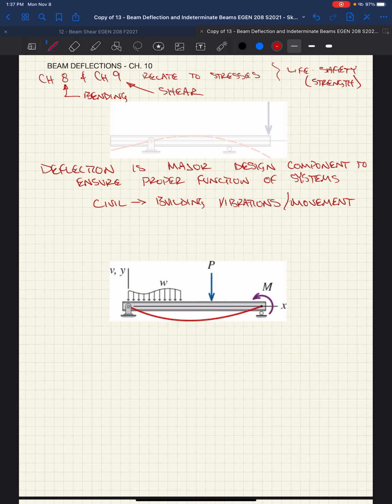So I've mentioned in the past, like ponding of roof systems. If it rains, the roof deflects. If the roof deflects, it no longer sheds water, say to the outside edges, scuppers or something, right? Those are those little discharges you see on the sides of walls and buildings, right? So if the scupper then becomes at a higher elevation than your deflected roof system, you're going to create a pond. Well, the pond brings more water to the center of your roof system, which makes the deflection worse, and it just exacerbates itself. It just goes on top of each other, right?